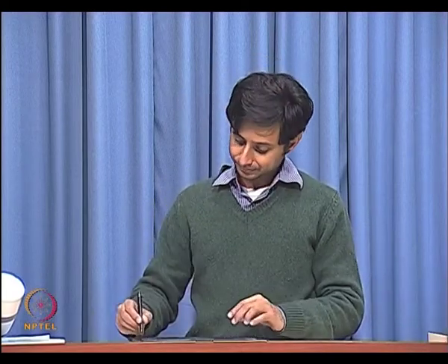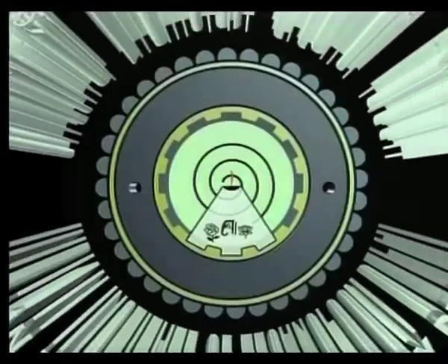On the other hand, the loop bandwidth cannot increase forever. The loop bandwidth can be at most something like a tenth of the oscillator frequency. Now, that means that when you build your phase lock loop, you would like its loop bandwidth to be exactly equal to a tenth of the oscillation frequency, because otherwise you lose in terms of performance. So, with this understanding we are going to proceed in the next class. We have kind of tried to build a phase lock loop. I do not exactly know if you completely understand what is going on over here or not, but we are going to see more of this in the following classes. Okay, thank you.